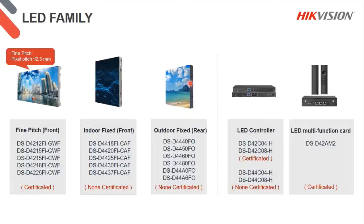All right, the LED family that we have, we've got indoor and outdoor versions. So you can see the indoor version over here, outdoor version over there, which means it's completely weatherproof. But the other difference between them is the mounting type, so installation. So you can see that this type of monitor over here, these LED blocks, is front mounted, which means you don't have to have space behind the monitors to walk in there and do your wiring. Everything can be done from the front.